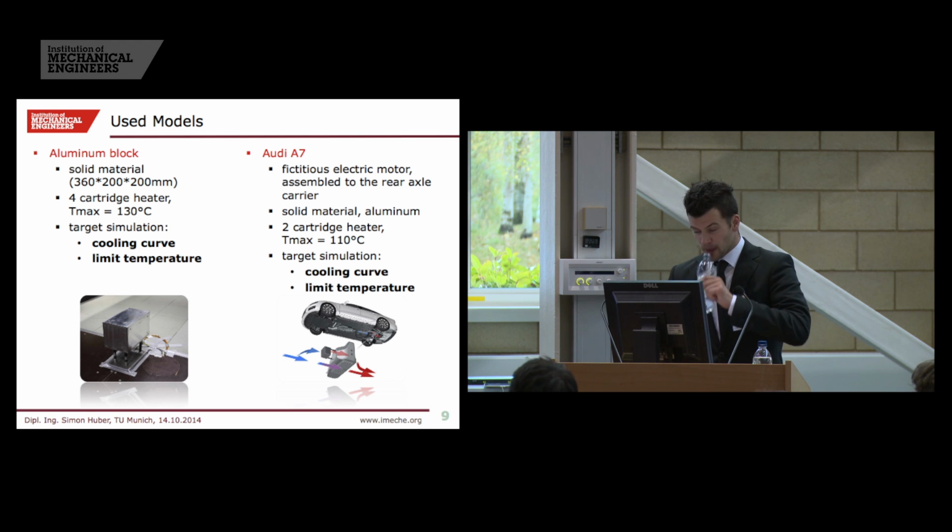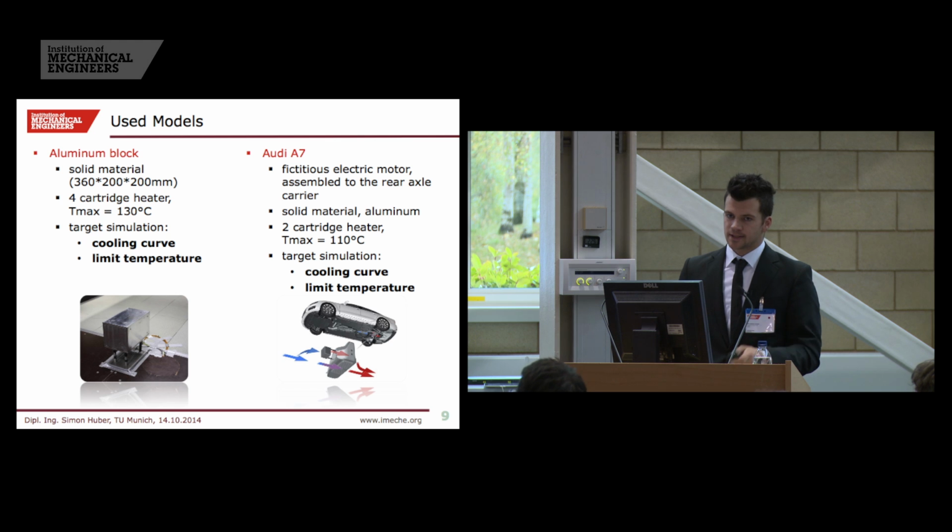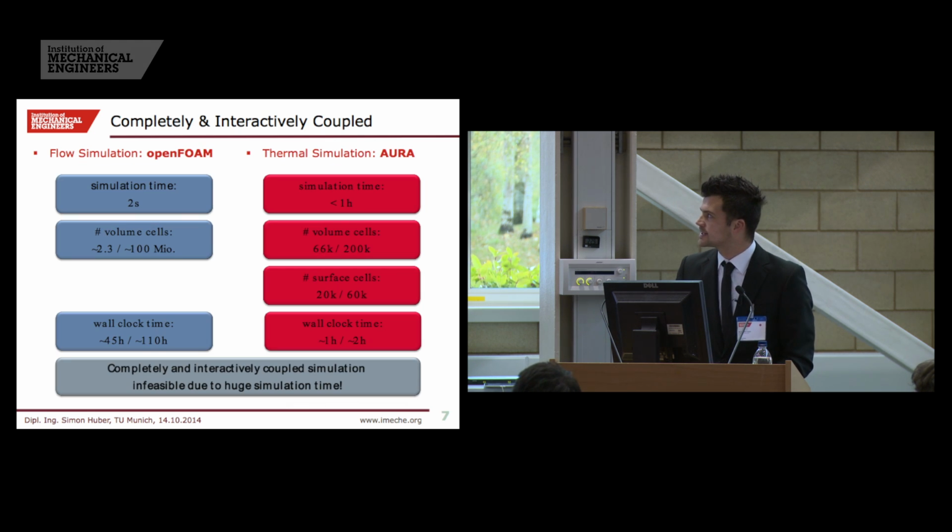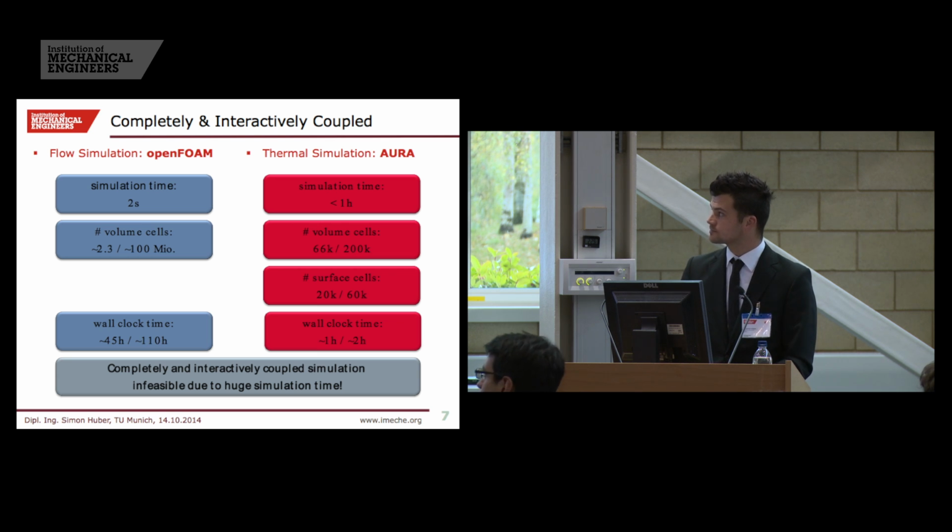So how can I couple the aerodynamic and the thermal simulation? This one is not easily done. If I compare the simulation time for the CFD simulation, normally we simulate 2 seconds of physical time. For the thermal simulation, I would like to simulate up to an hour of physical time. So you can see that this is quite a huge difference.